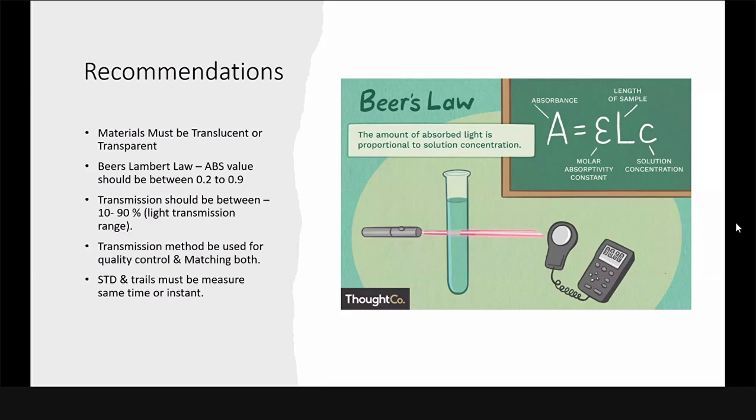We also can do formulation with the transmission measurement. In that case, we have to prepare the database in transmission mode, and then we can prepare the primaries as we do in reflection. Primary means multiple concentration data through transmission measurement, and those we can define as a colorant, and then we can go with the matching as well. So that is also one more effective method before formulation. It will have very good results as well.